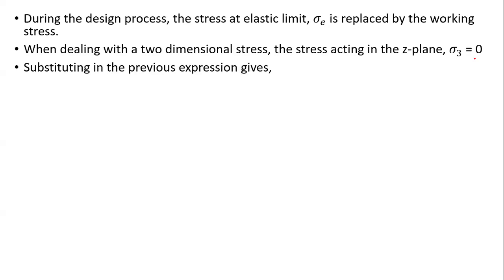With that being the case, we put back in the equation, therefore we have stress 1 squared plus stress 2 squared minus 2 over m, the stress 1 stress 2, is equal to this. This is the one we were saying can even become stress T, or just stress, being the working stress.